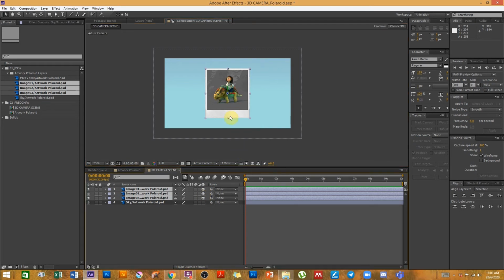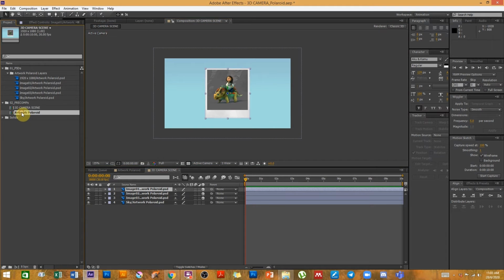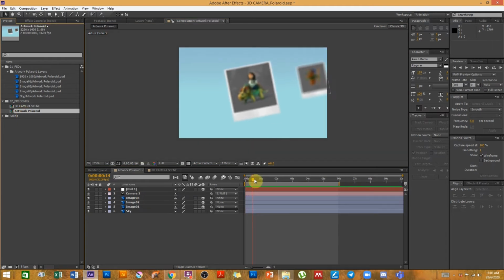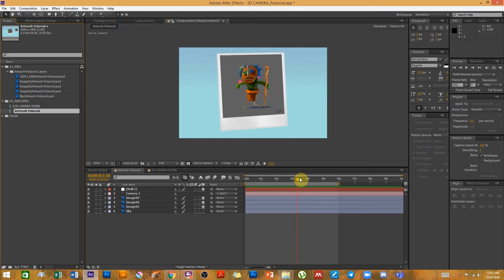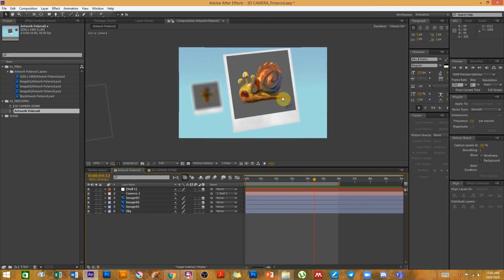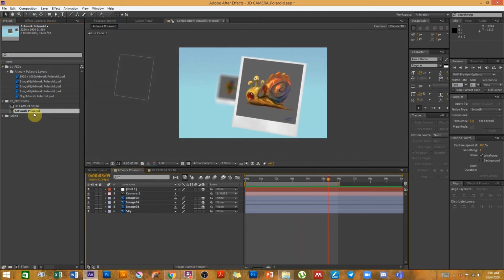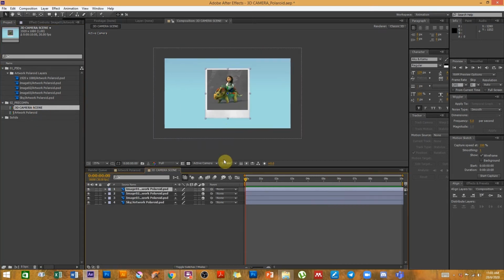And you can't see that it has turned 3D yet, other than the fact that you can see now that it has 3 arrows. The blue arrow, if you roll over that, is the Z-axis, to move it. The green one is to move it in the Y-axis, and the red one on the X-axis. So in order to change the location, I want to disperse them, as you can see in the earlier example, where they are placed in different places in this environment.